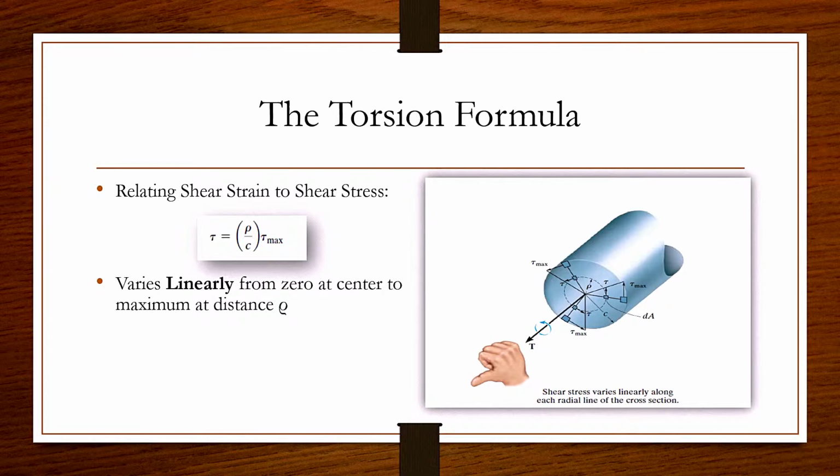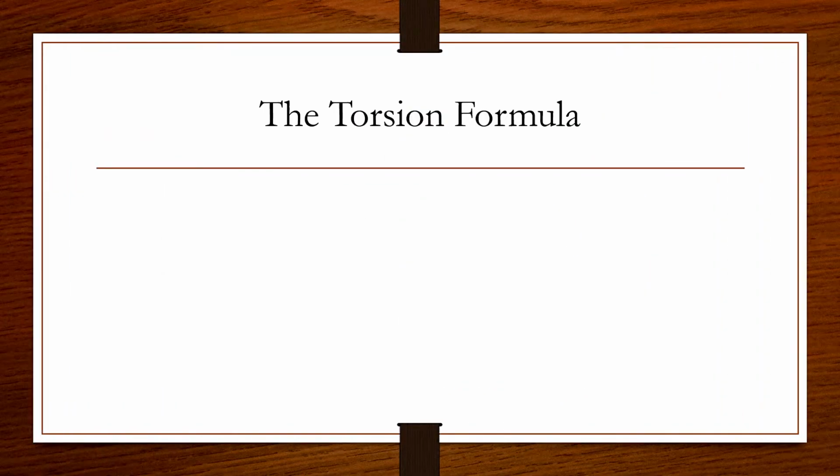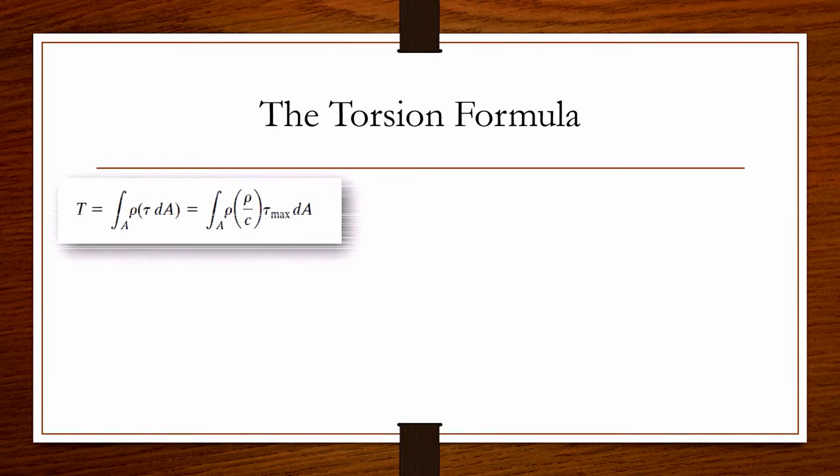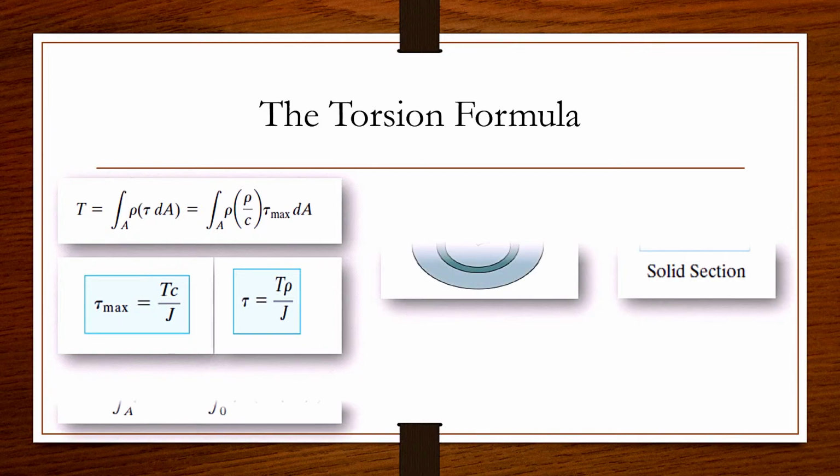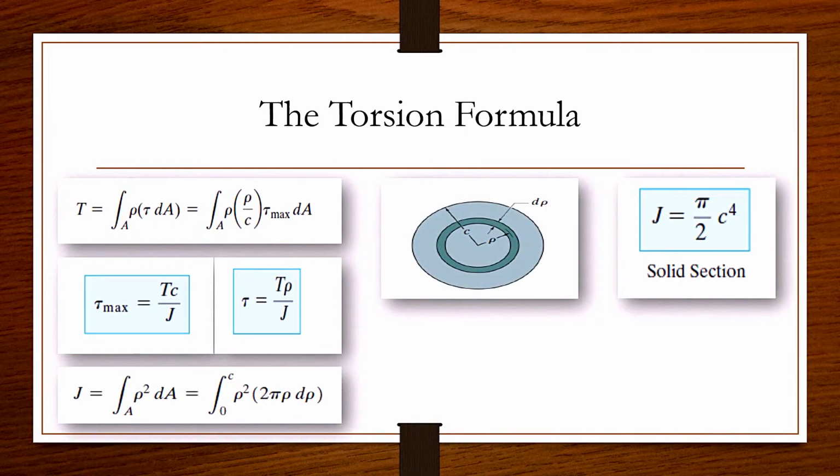As we said earlier, torque is mathematically known as a force being applied perpendicularly at a certain distance away. Torsion is therefore dependent on the stress applied over the area that it is concentrated over. Here, the max stress and the radius of the rod is a constant, so the integral to find the torque depends only on the radial distance of the shaft and the change in the area at that radial distance that we choose to specify. We can collect these like terms and call them J to simplify the formula, so it can be seen as the following. This is commonly referred to as the torsion formula, which will be how the software will calculate the torsion for your models.